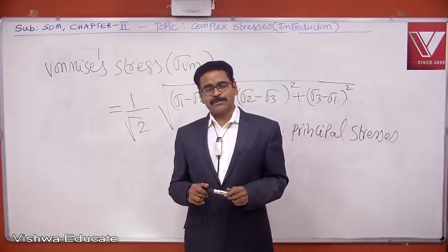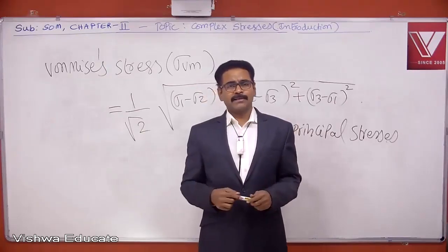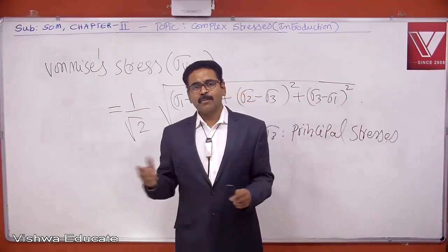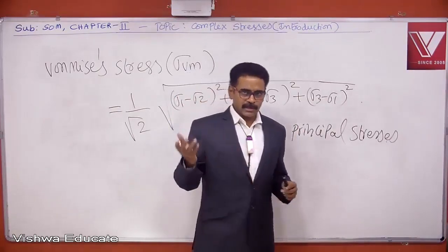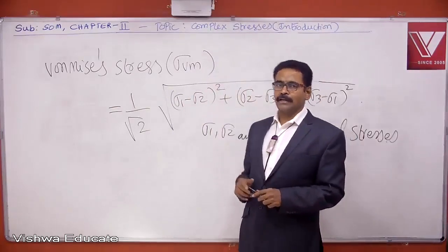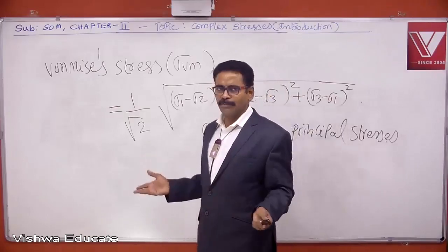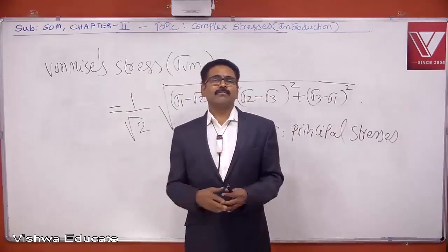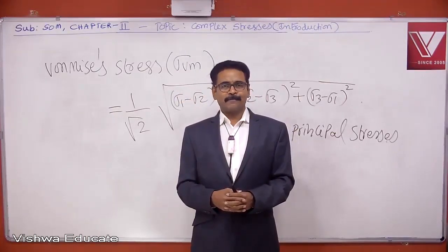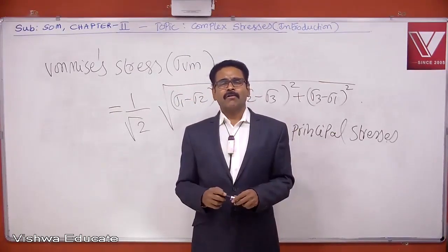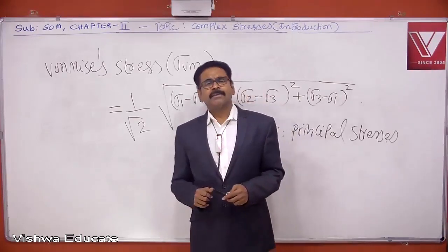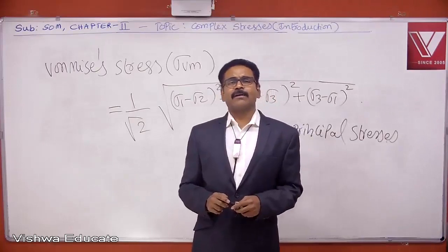Tests are of two types: destructive tests and non-destructive tests. With non-destructive tests like gamma ray analysis, X-ray analysis, ultrasonic, dye penetrant test, etc., no problem. We are not going to lose our components or assemblies. But in destructive testing, we may lose our product. For example, on every car, the car manufacturer has to run a number of tests.